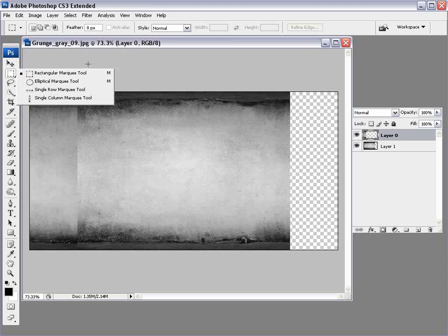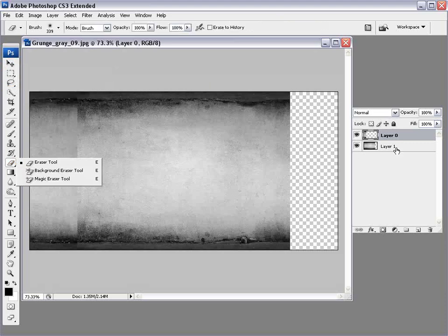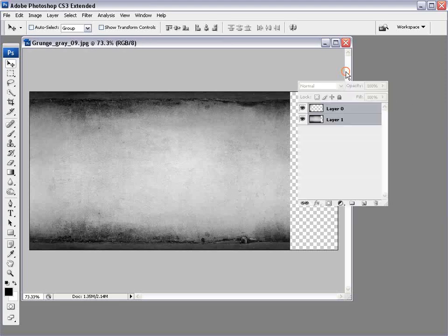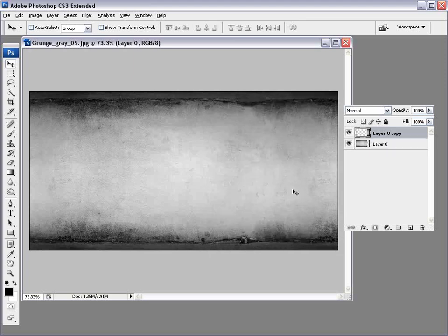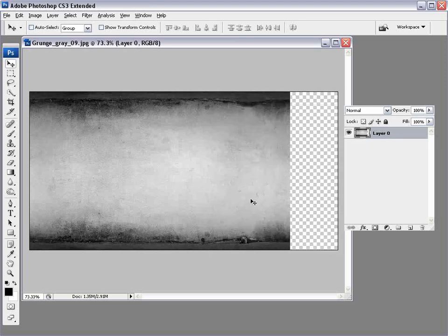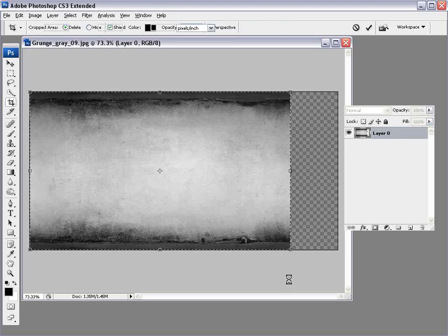And I'm going to go ahead and feather the edges of this. I'll just make it simple: we'll take the eraser tool and erase the edges. And then we'll take the layers again, and we'll merge layers. So now if I were to copy the layer, check it out. It hooks together perfectly. And when you're in 3D, you want your textures to be perfectly tileable. And so that's the purpose of this. I'm going to crop it to the end of that.